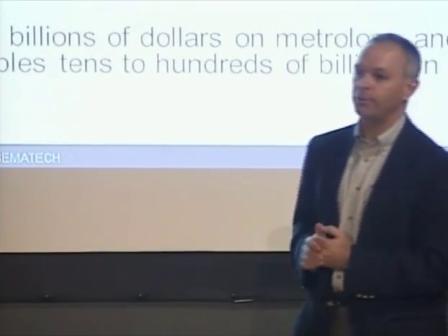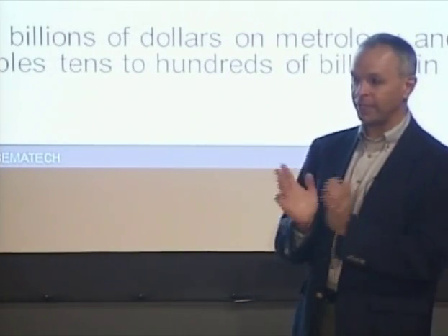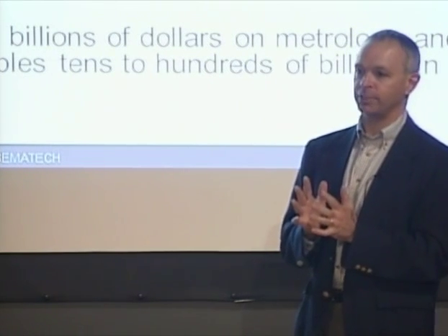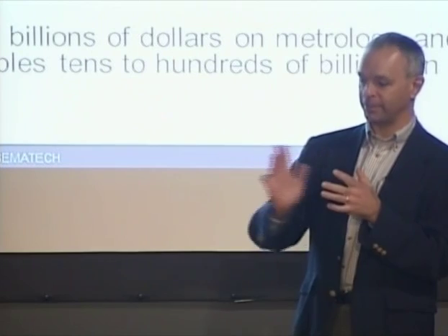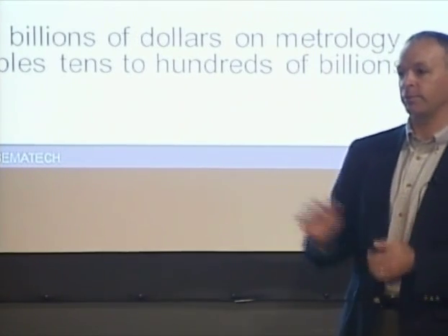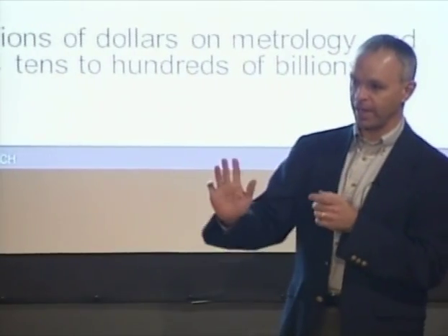So you asked, what are people doing? There's a couple things. They're trying to engineer the photoresist materials with different compositions to try to minimize that in the beginning, or find ways you can smooth it after you've generated it. So if you have a rough line, particularly if it's high frequency roughness, is there a way you can smooth it? There are some techniques people have looked at for doing that as well. So it's a combination of engineering new materials and trying to apply additional techniques for reducing the roughness.